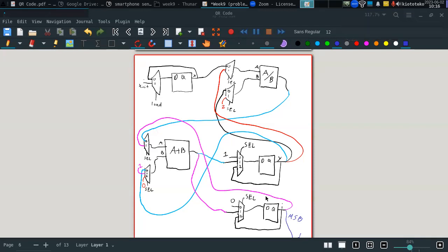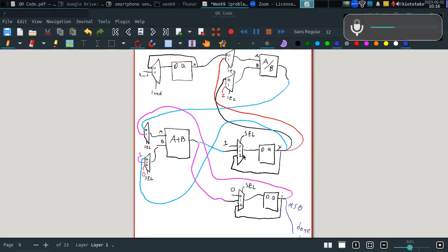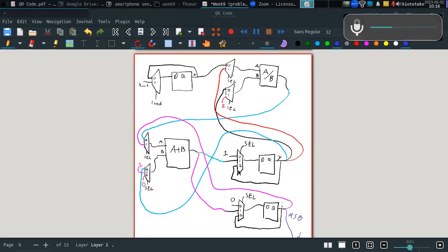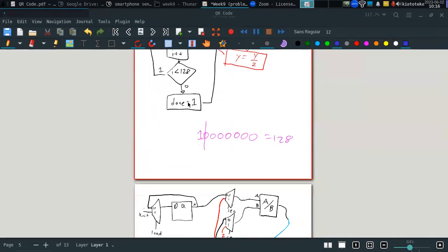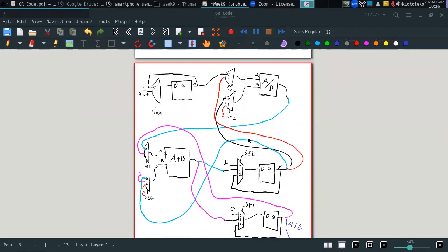What would you put for the selectors in the multiplexers to make sure that they're computing the first and the next combination? That's part of the controller, and we still need to design that, no? Because obviously this circuit is missing the control over the selector signals, no? If we don't have that control, we don't know what this circuit is doing, no? That is why we have to create a finite state machine that, based on the inputs and based on this logic, is able to control these selector lines, no? But we still need to design that.